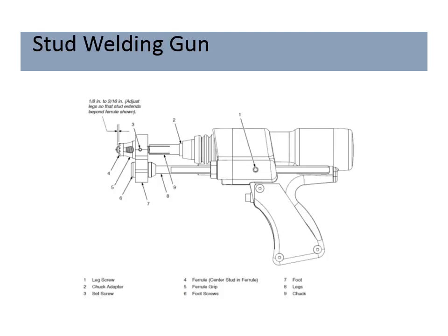For those of you that aren't familiar with stud welding, you use a gun. It's like a little pistol. And you take a stud, which is basically like a big, bulky nail. And you're going to run a bunch of electricity through it. It's going to go down and touch the base material. It's going to draw back just a little bit, create an arc. The end of the stud is going to get liquid. And at that point, a timer is going to go off in the gun, and it's going to jam that stud with the melted end into the weld pool.